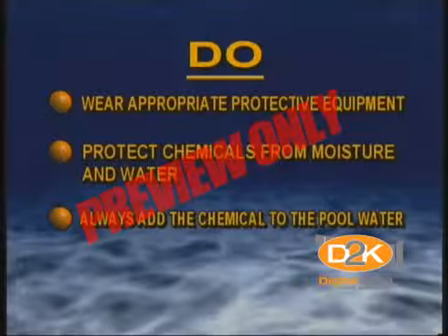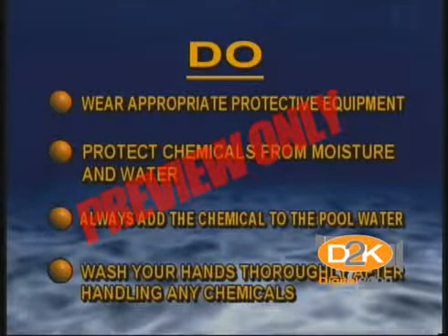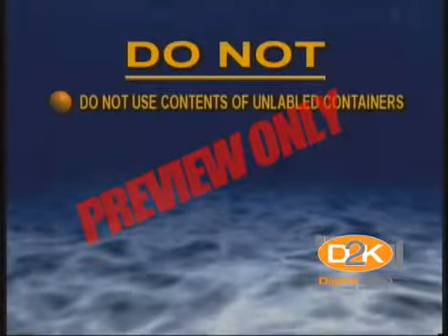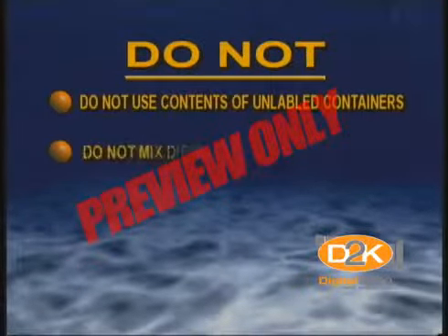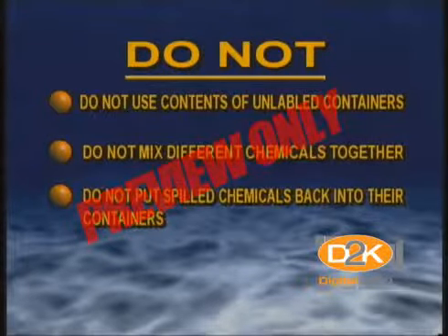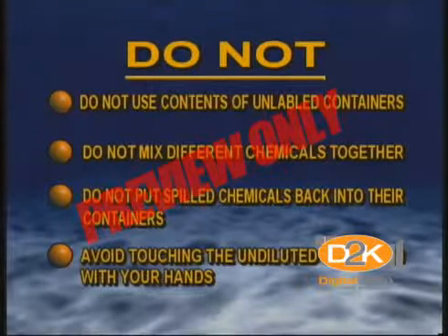Always add the chemicals to the pool water, never the other way around. Never add water to the chemical. Wash your hands thoroughly after handling any chemicals. Do not use contents of unlabeled containers. Do not mix different chemicals together. Do not put spilled chemicals back into their containers. Avoid touching the undiluted chemicals with your hands.